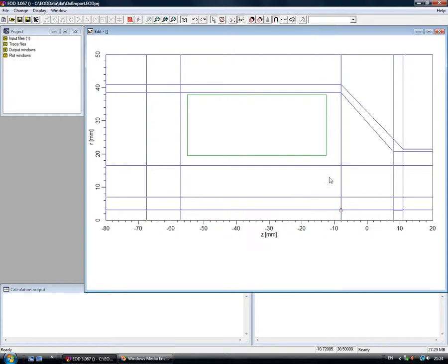We can create some other coarse mesh lines to put the coil in the proper position. Okay, but I first need a vertical mesh line to move the point to the corner, so I should create one and move this point to the proper position and align it to have the correct position of all coarse mesh lines.